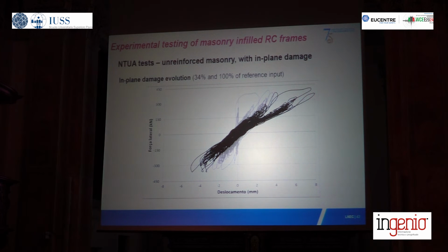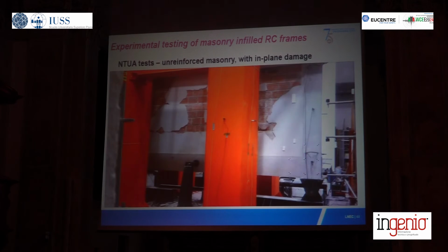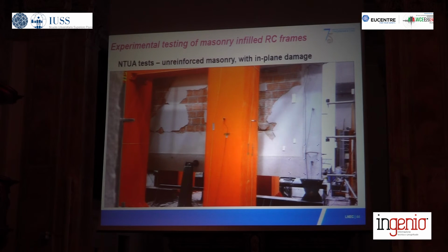Here an example of the difference between the cyclic response in-plane for two of the stages, and the video of the test when we were doing the final stage of testing, where you already see that the out-of-plane frequency of vibration is pretty much reduced. You see the sliding at the 2 horizontal cracks, and you see some damage occurring at the upper bricks on the right corner of the figure as we impose the seismic action.